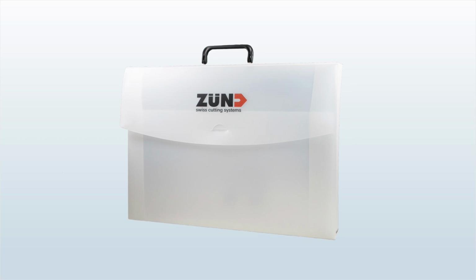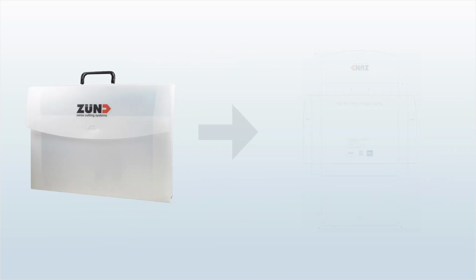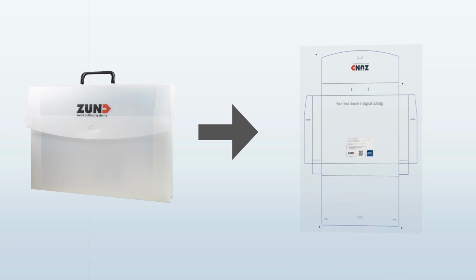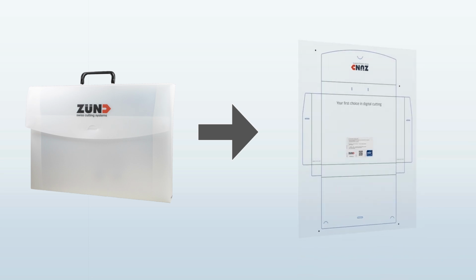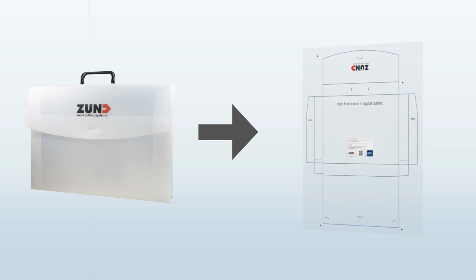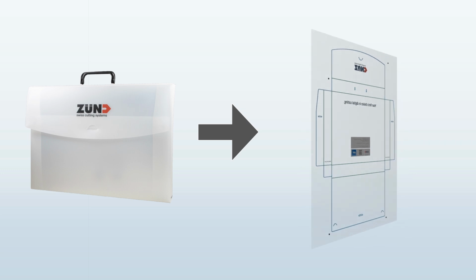To show you how to handle action steps in the ZCC, we will now have a look at a specific job and carry it out with the help of predefined actions. So here is the scenario. We're going to produce a carrying case made of polypropylene. For the job, we process identically printed panel materials. This means that cutting paths and register marks are always in the same position. We want to produce a large number of carrying cases, so we are using the board handling system. The processing is to take place on the rear side to improve the quality of the processed edges.